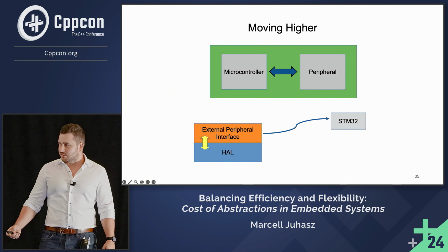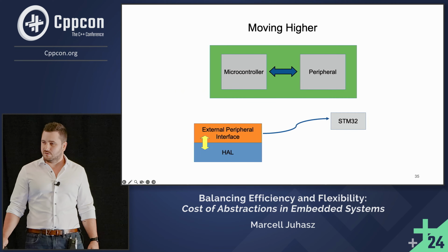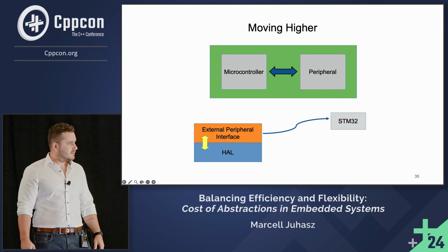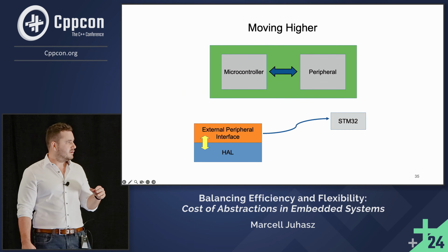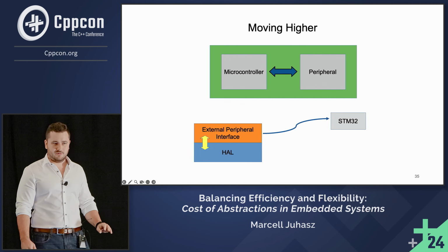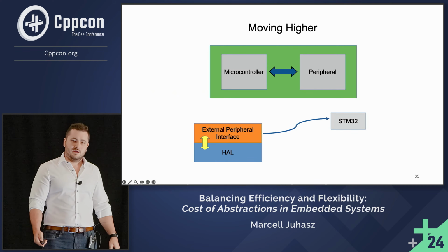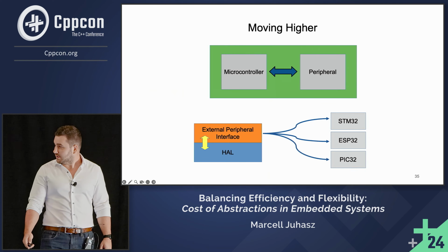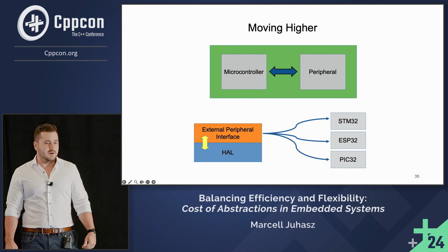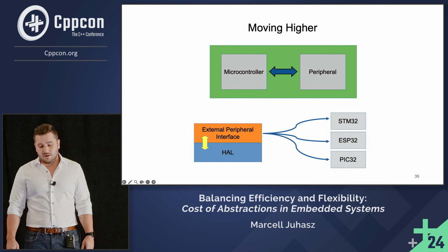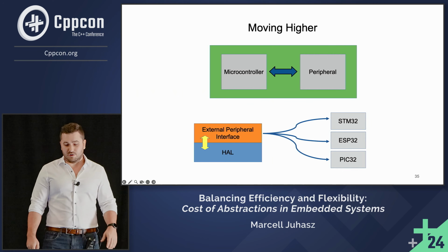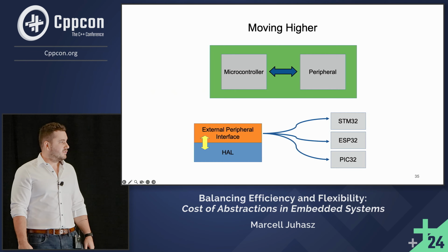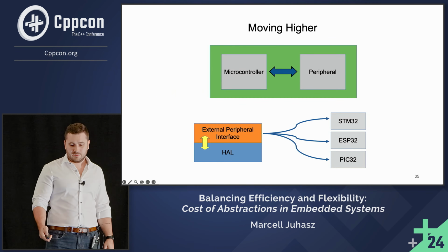So if you wanted to port this piece of code between different devices of the same manufacturer, then it would probably be pretty simple, because the interface of the hardware abstraction layer is kept consistent exactly for this reason. But problems will arise pretty quickly if you want to port this code to a device from another manufacturer, because now you have to port the whole implementation of the external peripheral interface, and it can be very time-consuming for complex peripherals.